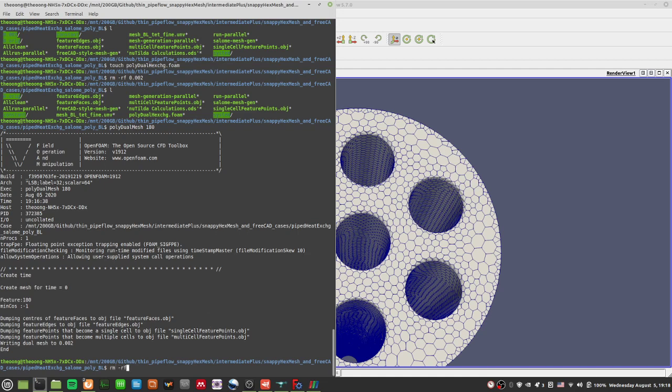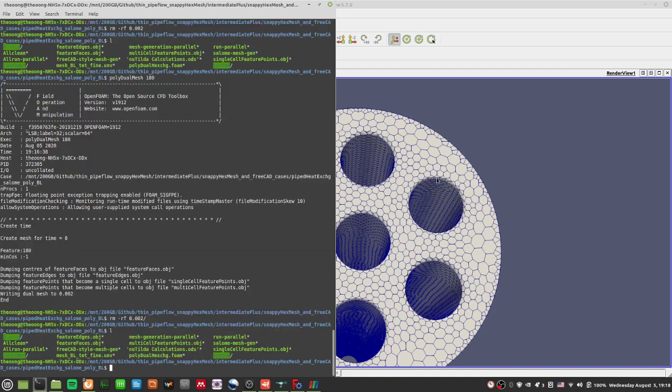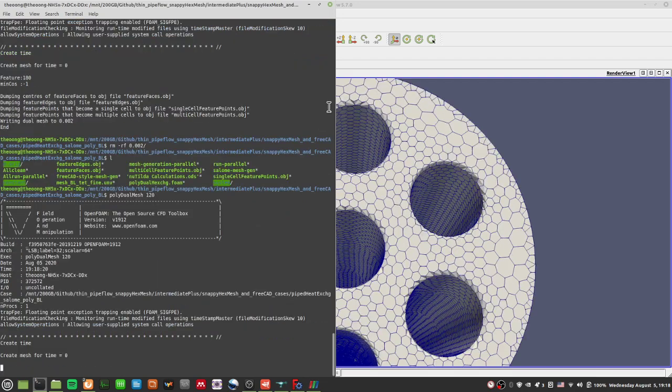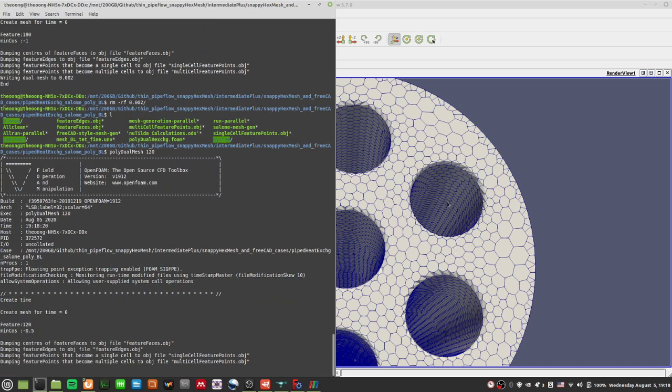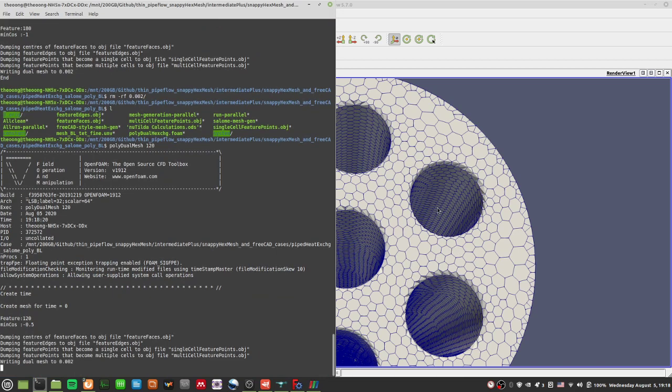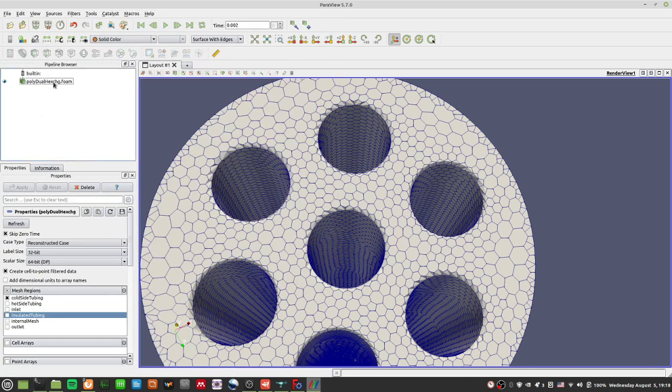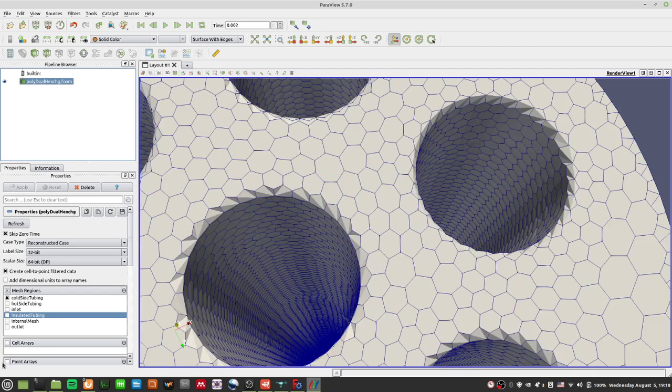Because this bend here is 90 degrees, if I do 120, I will still get the same check mesh. It's the same kind of mesh with the same features, and you will find it's exactly the same shape, because there are no really sharp angles of more than 120, since this is 90 degrees. You can see all these sharp edges are still not being captured as sharply.